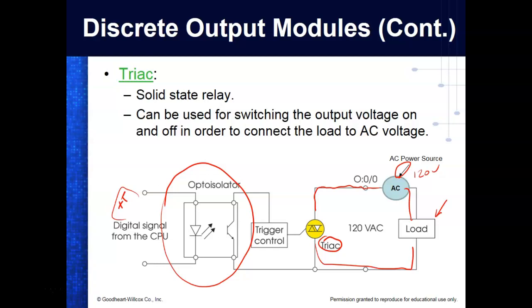I can do that with a light switch. Well, what do relays do for us? It's a magnetically controlled switch, but what can we control with the coil of a relay? We can control AC, we can control DC. So the contacts on the relay, the voltage controlling the coil and the voltage across the contacts do not have to be the same, right? You understand that? It's just like you and that light, that what you're switching over there are not the same thing, right? I can go over there and switch it, or you can go over there and switch it, right? That switch could be controlled.